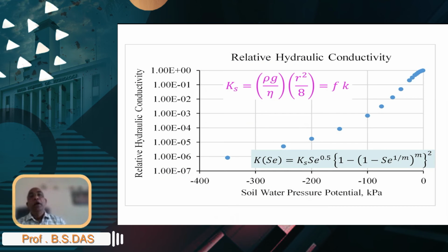So under this steady state, this hydraulic conductivity has to be a function of the potential head. As I was mentioning earlier, because the water containing pore size is going to reduce, the corresponding H values are going to become negatively larger, right? Water content is going to go down. So similar to a water retention characteristic, you will get a characteristic curve for the hydraulic conductivity as a function of the pressure head, or a function of the pore size, or a function of the soil wetness.